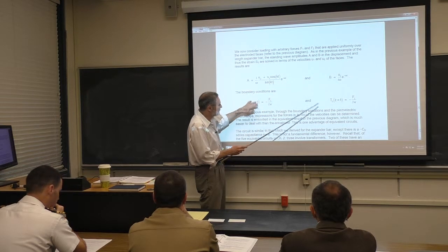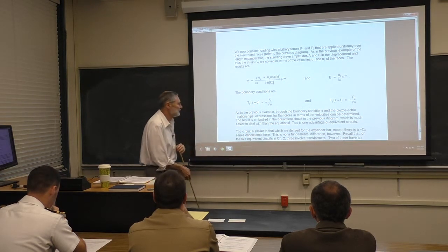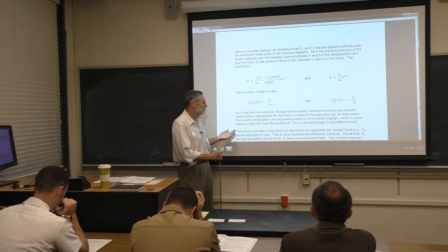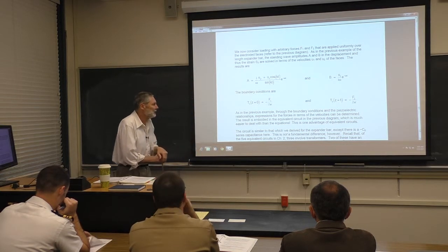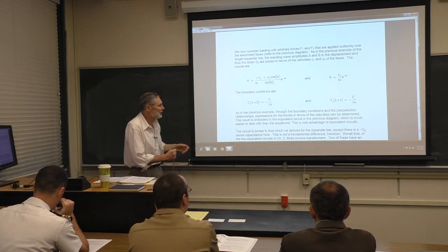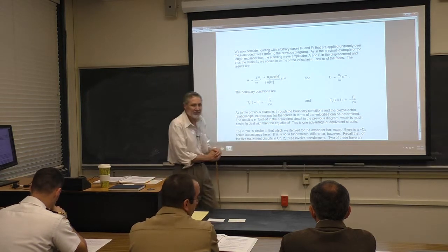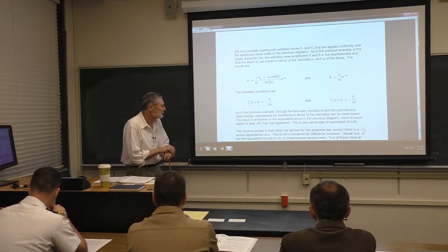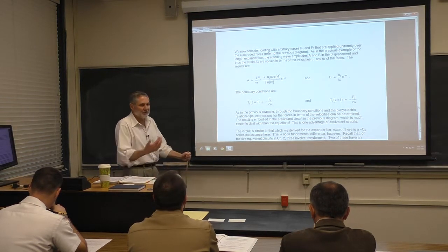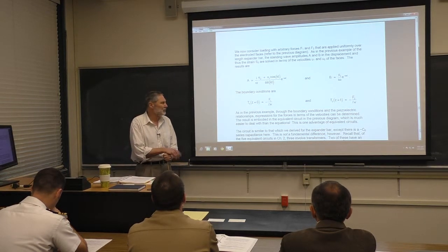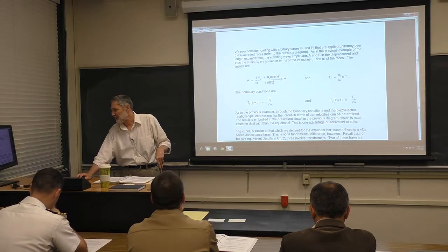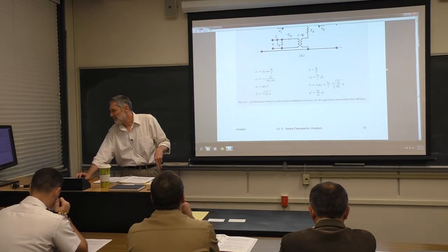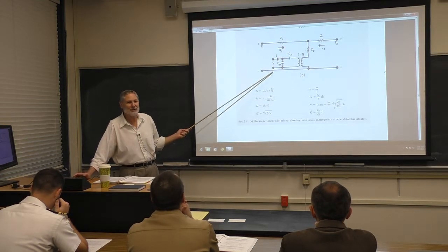now with the force being in here, we need to express this in terms of velocities at the ends. So from the piezoelectric relationships, you can get expressions. In canonical form, it would be the forces in terms of the velocities. That's the canonical. Remember, first thing in chapter 2. And you get these expressions, and they're somewhat lengthy, I seem to recall. But we don't care, right? Because they're all embodied in this equivalent circuit. You can show that this is the equivalent circuit.